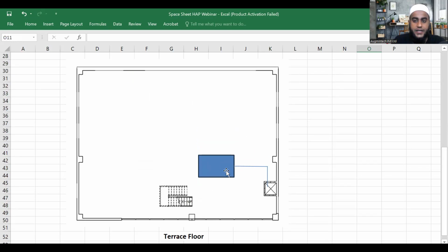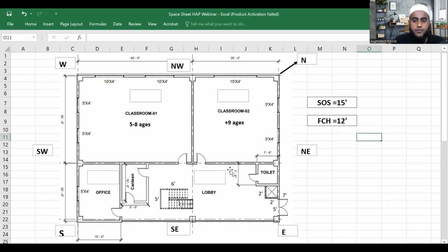So what we have to decide here is which type of unit you want. Before starting the calculation, first you have to do the selection. Remember, our main target is to calculate the cooling load value and supply air CFM. As per that, we have to decide which type of air conditioner unit to select: air handling unit, FCUs, or what. Let's say I have decided to select the AHU.